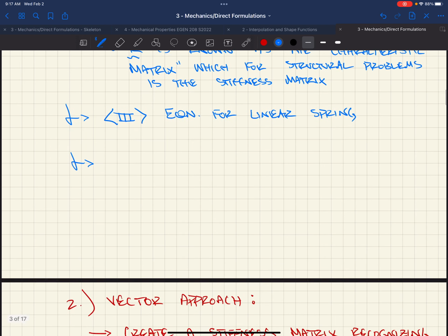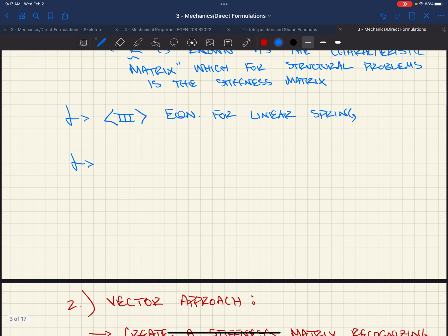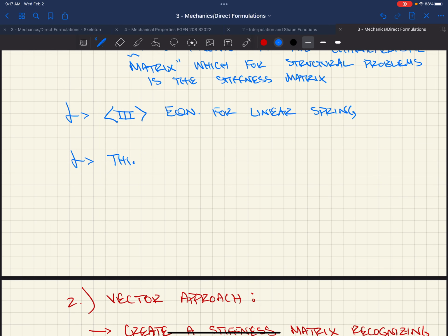And something to think about: thinking about all structures as a system of linear springs isn't a bad approach. Stiffness attracts loads in mechanics of materials. Everything has a stiffness. It might not be an axial stiffness, it might be a bending stiffness, a torsional stiffness, a rotational stiffness. But everything has a stiffness associated with it. That stiffness, driven by displacement, gives you force.